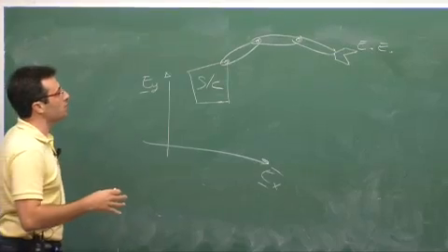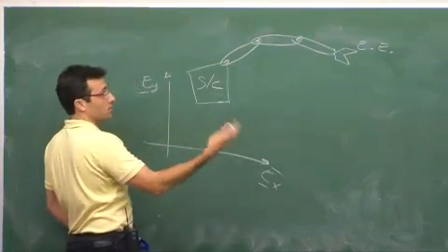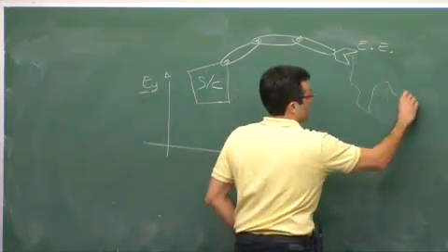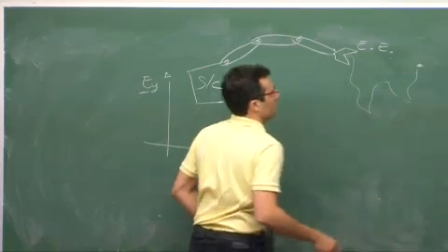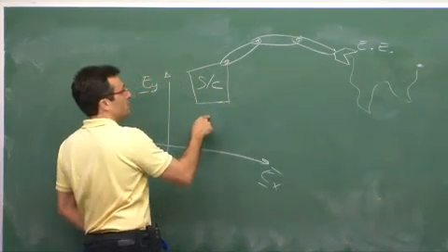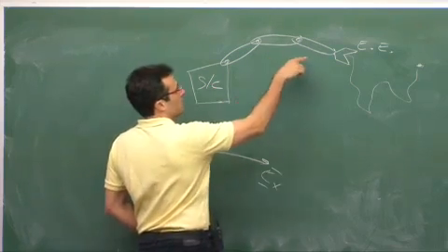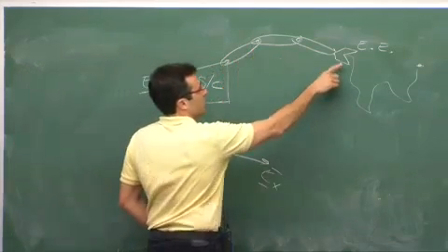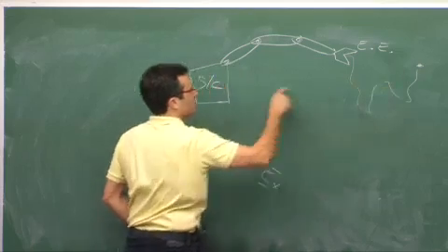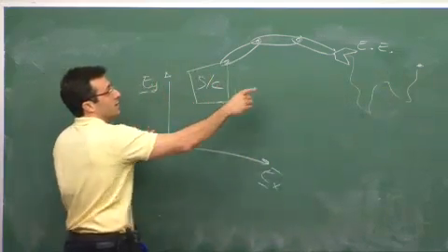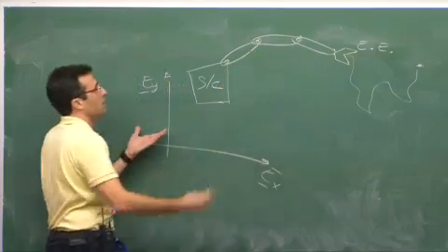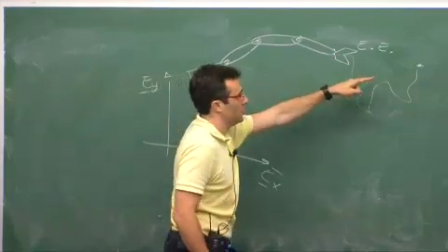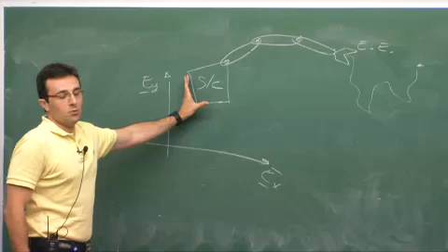What you want to do is control this system. Controlling this system really means this end effector is going to follow some trajectory and reach some desired point in the inertial space. But you need to maintain some control on the base. You can't have these links moving and the base going crazy. If you start actuating all these links, there are internal reactions that will make all the other links move, and so the spacecraft will go away and you will never drive the end effector where it needs to go. If this was grounded somewhere, that would be easy.